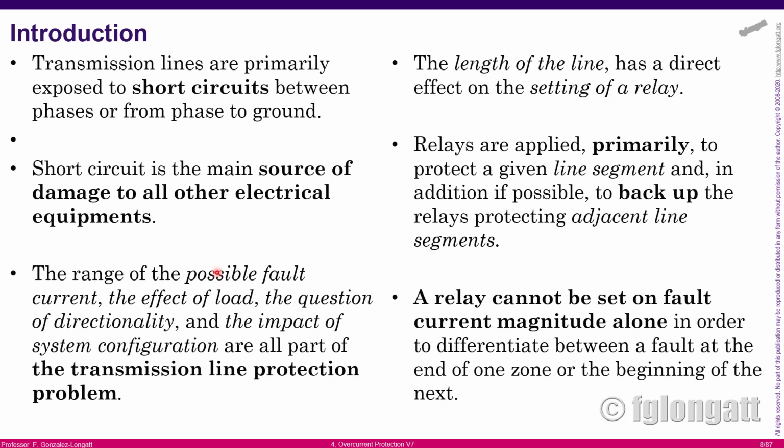Okay. We need to be clear that there are many kinds of faults. Some of them are related with the loads. Some of them affect not only the magnitude of the current, but also the directionality of this current, especially in mesh systems like transmission lines. For that reason, as you can see, transmission line protection using overcurrent is a bit more complex problem, especially because of the directionality of the currents. Okay.